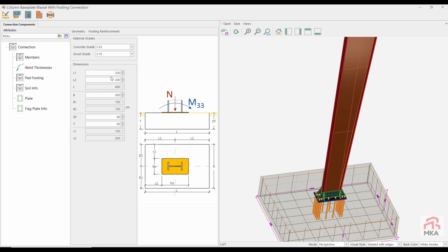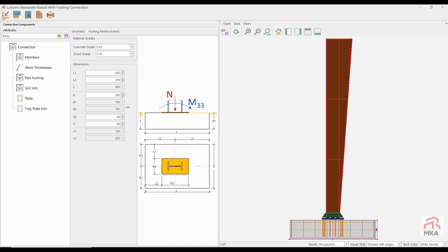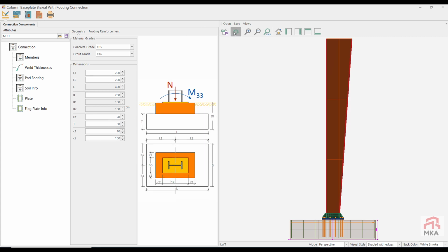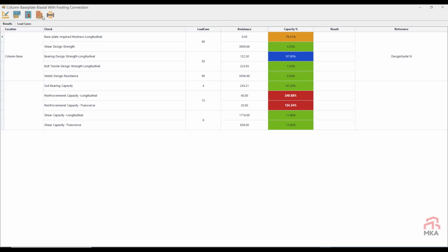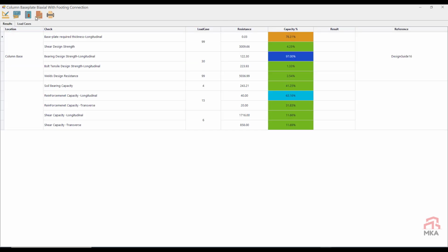The foundation used here is 4 meters by 3 meters. Let's make it 4 by 2. Now let's fix the reinforcements of the foundations. Let's set rebar diameter as 24 millimeters. They are 14 centimeters apart. Again, I make sure that it is under 20 centimeters. We can reduce the numbers a little. Let's reduce the diameter.